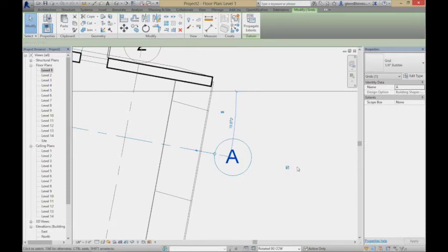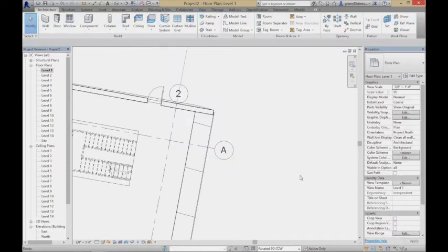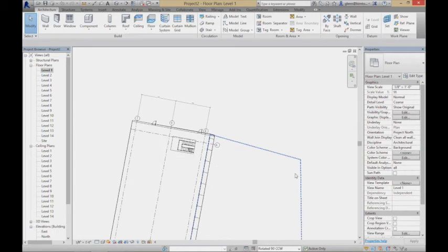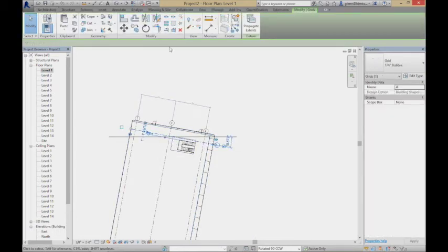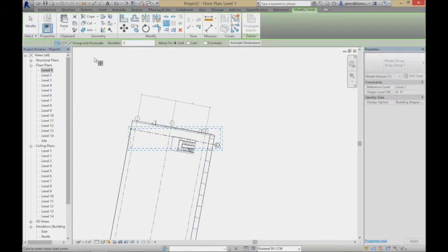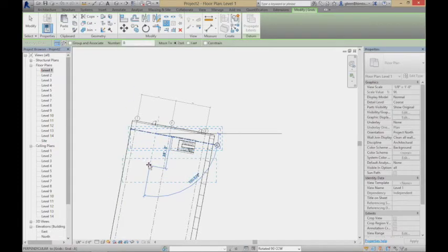Now, for this other one, if I have a very regular column grid that I want to put in there, maybe I'll even do an actual array. I like arrays. I'll say array it. I don't want to group them, so I want to keep them independent. I'm going to go through and put in like 8 of them. Give it some sort of distance, like 30 feet.